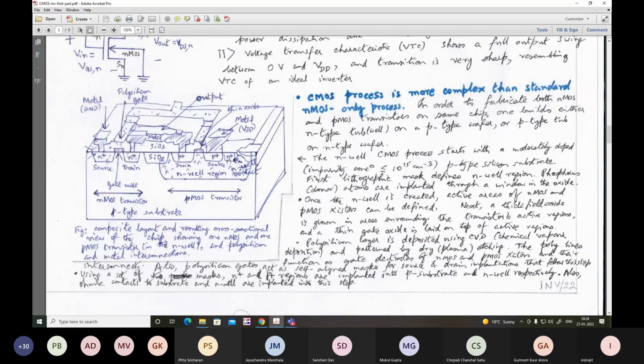So this and the source of the PMOS transistor should be connected to the power supply voltage. They will establish good isolation. Also, they will lead to a decrease of the impedance offered by the N-well. Similarly, here also on the P plus region, I have not shown it, but this is the ohmic contact. Ohmic means the resistive contact, that means a non-rectifying contact.